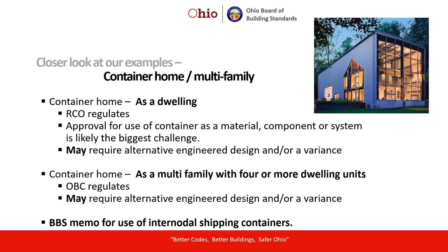There's actually a BBS memo out on the use of containers in construction, and it talks about evaluation service reports, and there's 3 of them out there currently that I'm aware of that talk about the way to get approval to use a shipping container or an intermodal container. It's very possible and likely that the use of that container, as you start thinking about cutting openings in it, as shown in the picture, that you're going to require a certain amount of alternative engineered design or some sort of variance, because most of the evaluation service reports do not address modifying the container.